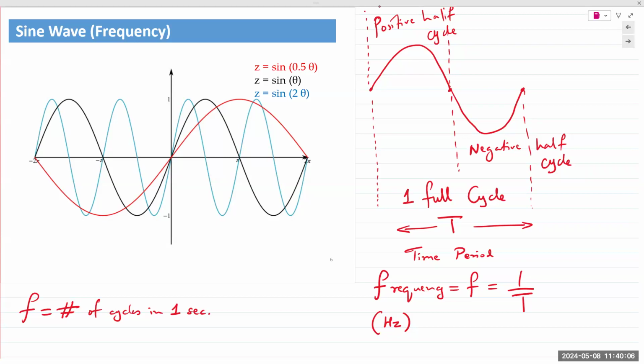Normal operating radio stations like AM and FM, the name of the radio station actually has a technical meaning. It is the broadcasting frequency of that radio station. So 680 AM stands for 680 kilohertz of the frequency of the broadcast. 101.7 FM is 101.7 megahertz of frequency of that broadcast station. So kilohertz, 10³, megahertz, 10⁶. Wireless routers, gigahertz, 10⁹. Microwaves, cordless phones, all 2.4 gigahertz or 5 gigahertz. So really high frequencies. The wireless routers and mobile phone signals that we use all run in the megahertz and gigahertz range, right? Very, very high frequencies. So 60 hertz is basically nothing, very, very low.